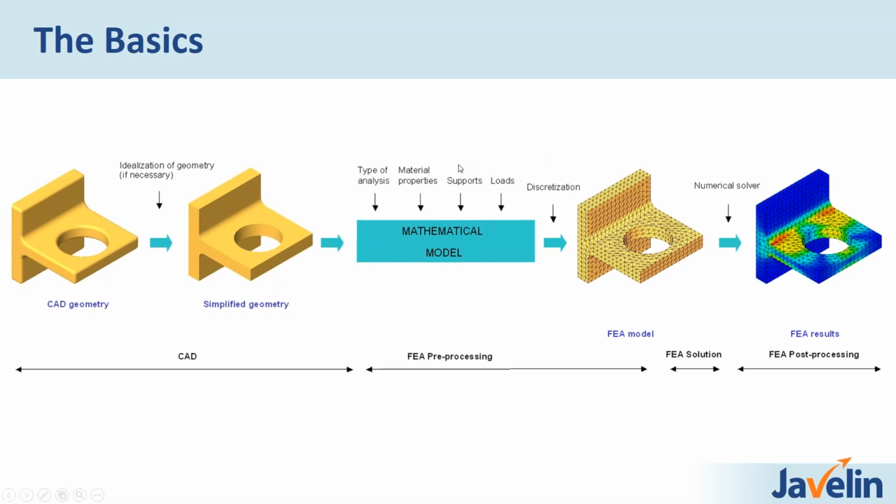Then we need to talk about our loads and supports. So how are we fixing the model or restraining it? And then what are we doing to introduce load? Is it pressure? Is it force? Is it a torque, etc.? Well, once that's done, the last step is mesh the model.